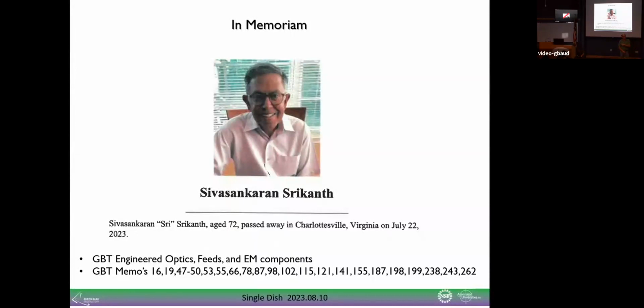After we get by the first amplifier, the signals are low. But as you increase in gain down the system, the RFI gets multiplied higher and higher. So we typically put some kind of notch filter downstream if it's really bad, like the radar, and that's how we deal with it. But it's always an increasing problem. RFI gets worse, and I'm trying to mitigate it.